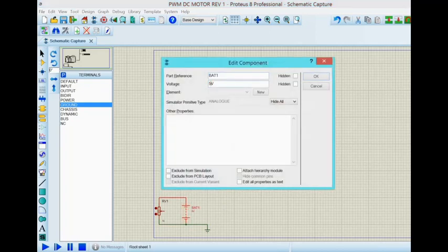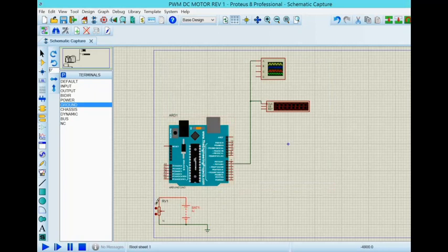That's going to the Arduino, and from this is the one that I need to connect to A0. That will do. So if I adjust this, then you will be reading that through your analog 0, and adjusting your code for your analog write that you're going to be putting right at port 6 of the fast pulse width modulation. I think that we have everything that we need so far.